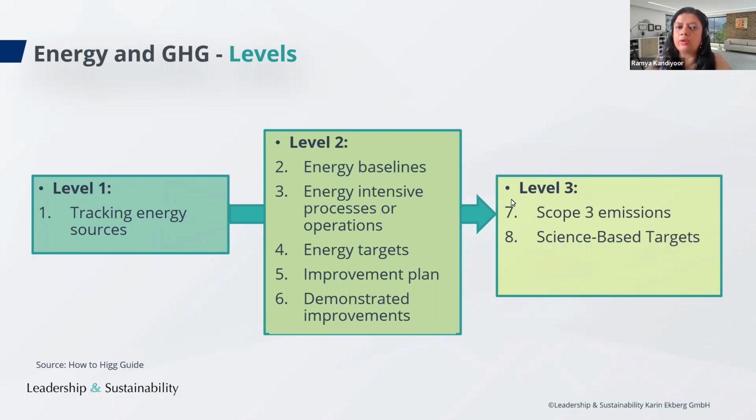Khanna. So what my suggestion then would be that you look at your production in the form of SAM, which is standard allowed minutes, which gives you a variability factor which you will be able to choose for each of the products that you are manufacturing. So this should take in the variability of the production. If you are reporting directly on maybe the number of products that you have shipped, you might not be in a position to normalize your data appropriately. But if you're using SAM, you would then be in a position to do so.